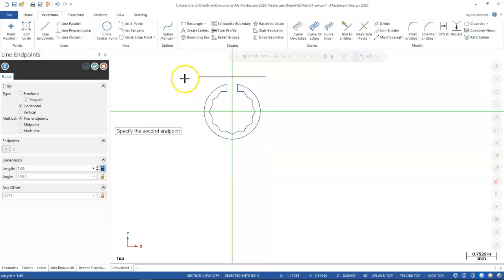All right, second endpoint, direction. Make sure to hit the checkbox. If you don't see it on the screen as a preview, I can't go on to the next command. I'm basically messing it up. Now when I switch to vertical and we tell it 6, it's still showing 180 in the angle. But it switched over and now it's showing an angle of 270. When I go up above the line, it's showing an angle of 90. So you should be able to click and accept.